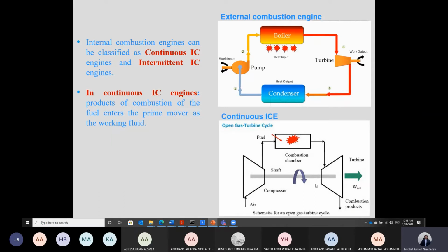What about the gas turbine? Shabab, I have to tell you that Saudi Arabia is the world's top country in using gas turbines. And it is used in electrical power generation as well. But usually a gas turbine is an easy unit to start and easy unit to shut down. So usually in a combined cycle power plant, we have both of them. We have a steam turbine to provide the basic load, and then as you know, the electrical power consumption changes from time to time. So I think here the top required load is at noon time, because air conditioning is working at the most due to high temperature, so we need extra power.